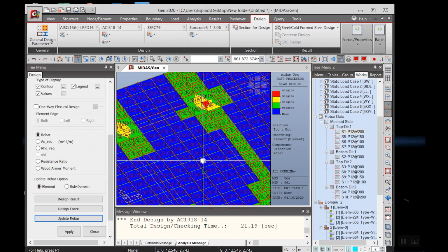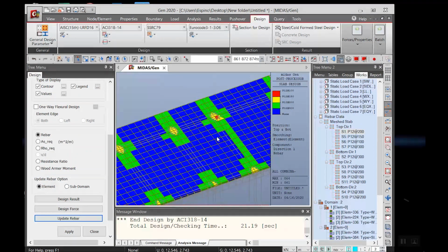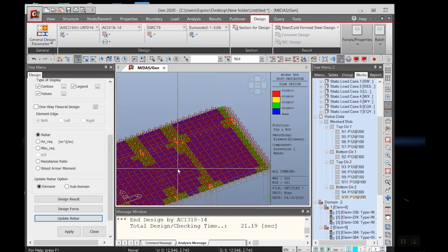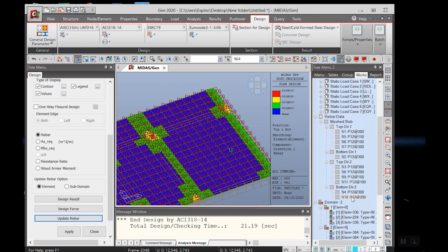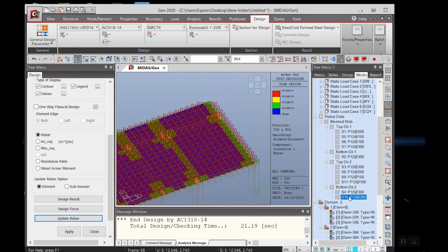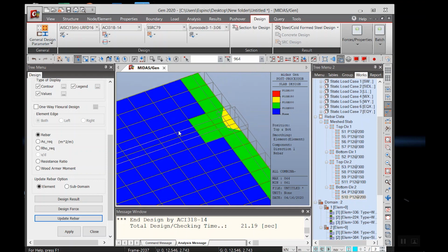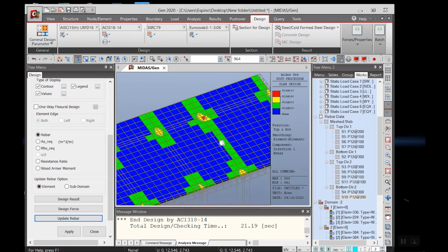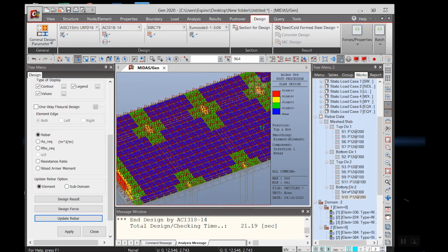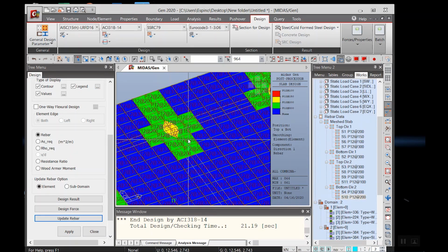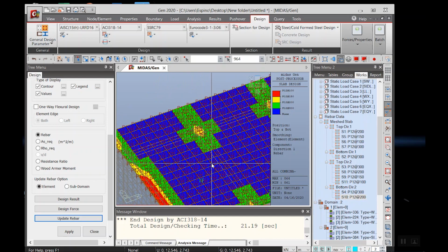After doing that, let's say I want to change a portion of this slab. We have a portion of slab which has 200 millimeter spacing. This portion actually requires a spacing of 200 mm for the bottom direction along direction 2. Direction 2 is actually along the y direction.